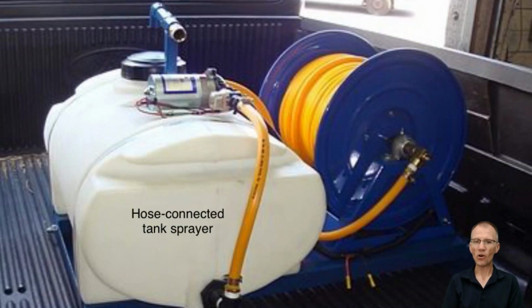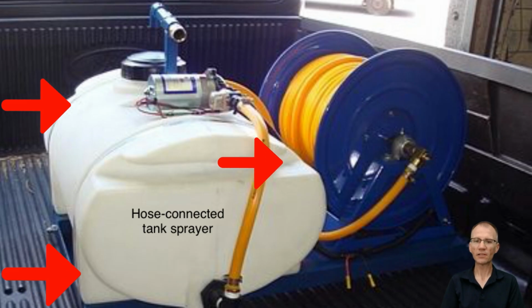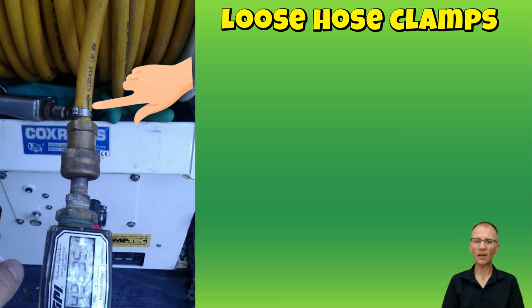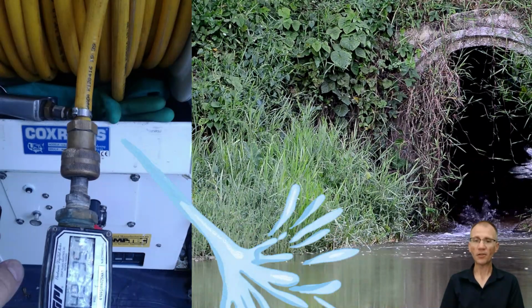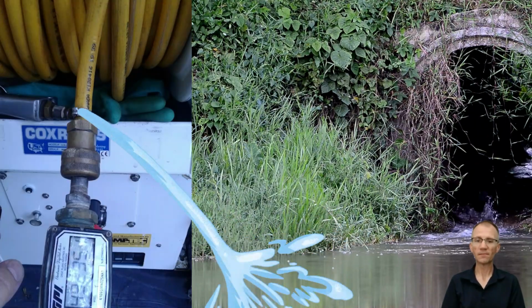When it comes to checking hoses, valves, nozzles, hoppers, and other equipment, always look at these hoses. I can tell you when it comes to doing applications for termites, when it comes to doing lawn spraying especially, these high-powered rigs can be a major problem. A hose clamp can come loose, a hose can split. Whatever happens, that product can start spraying out in a pin stream, or the whole hose can blow off, and then you'll just see a stream coming out of your vehicle, probably going to the nearest drain or ditch around your vehicle, and then you've got a major pesticide spill, and you've really got a problem on your hands.